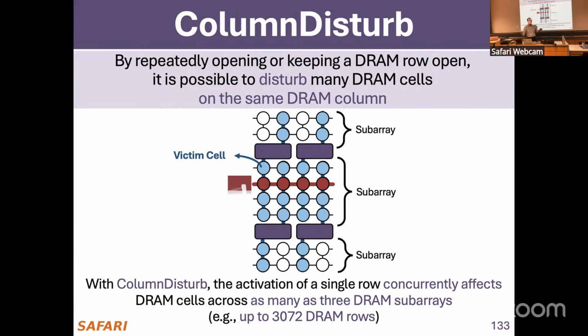Now this basically cannot be solved with existing RowHammer solutions. Existing RowHammer solutions, well, I guess BlockHammer is an exception. Okay, with BlockHammer, maybe you can solve it. But per row activation counting, for example, is not a good solution because it doesn't take this into account.